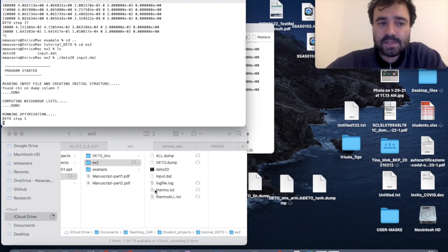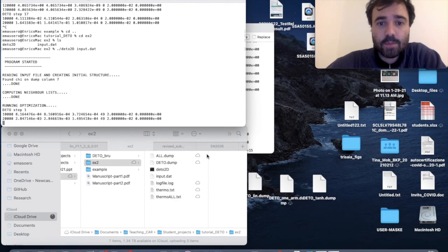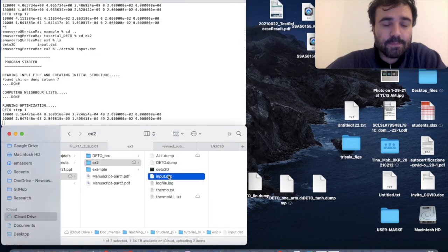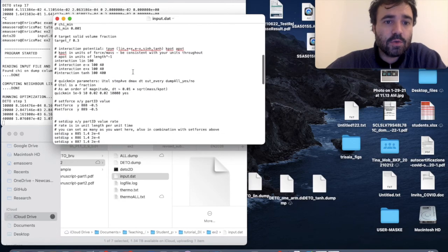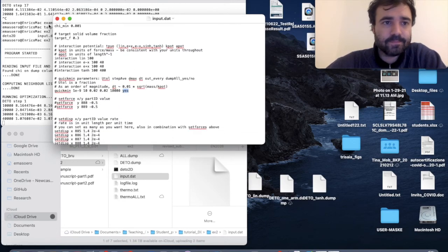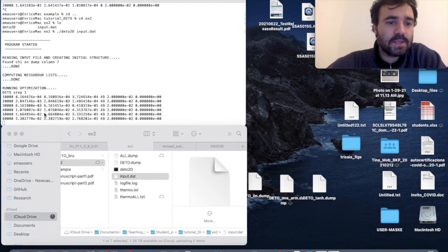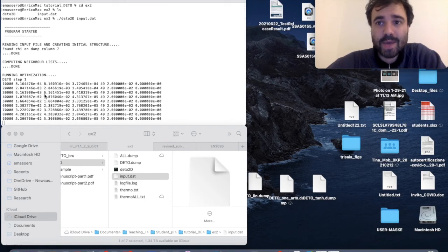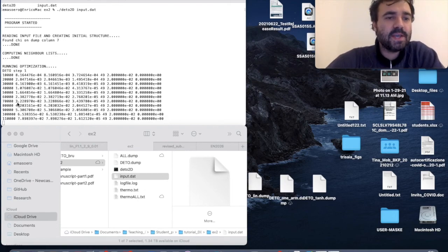And now it's saving. In this case, it is important that we save the old dump so that the option, sorry, wrong file, that in this input file you must make sure, because you want to create a force displacement curve, you want to make sure that this option here is yes. And now you see that it's accumulating steps. It's taking its time. We have imposed 1.4 displacement. Before we were doing 0.4, so we are using the same rate, so it will take a few more steps to actually conclude the loading stage.